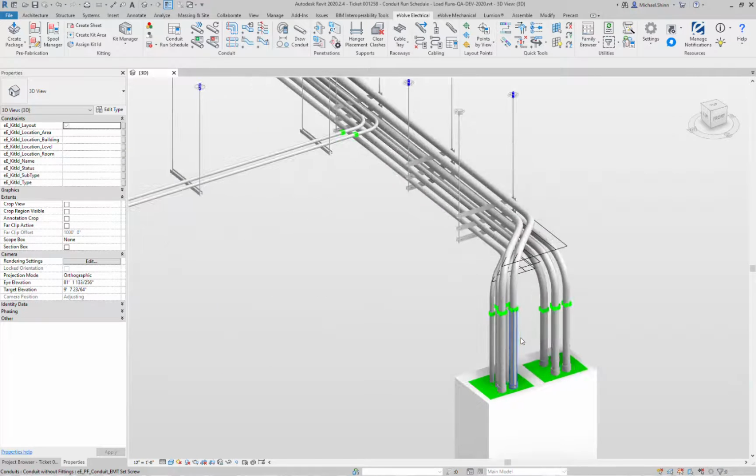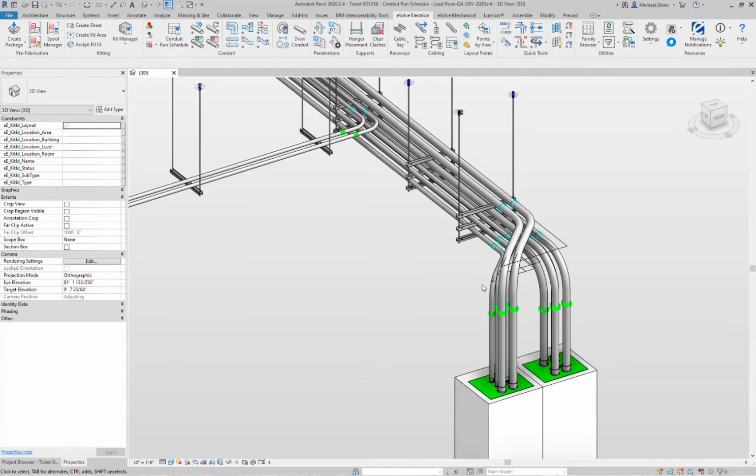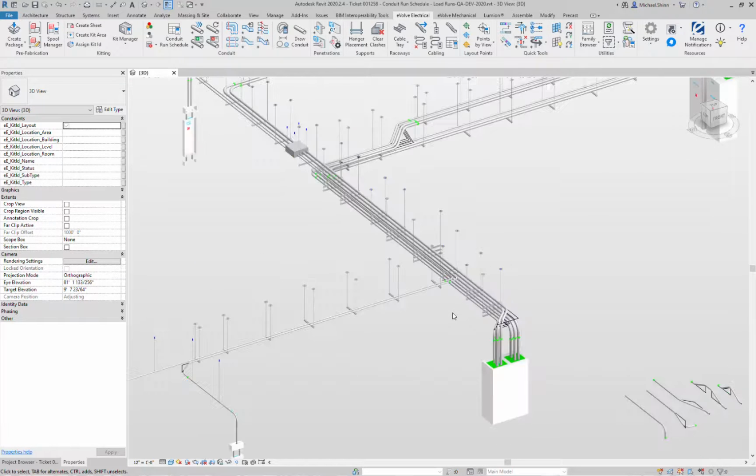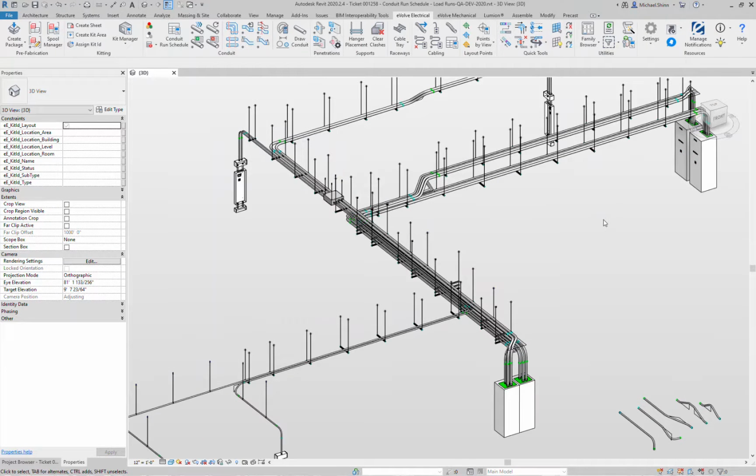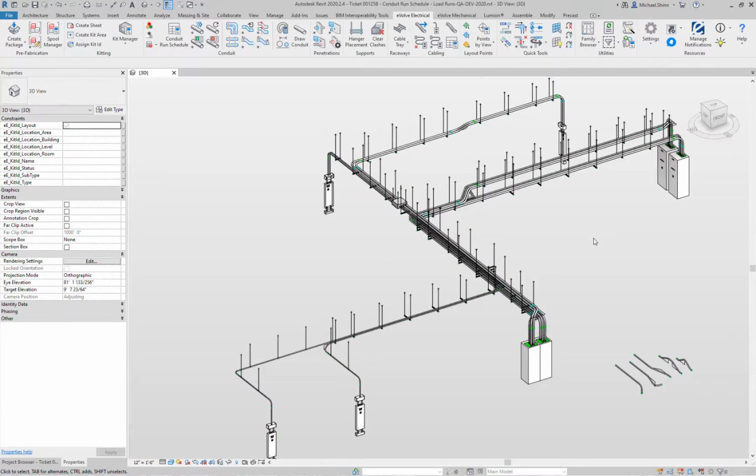In this case, you optimize your runs so that all of your bends and couplings are nicely aligned. This is the same method and procedure that takes place particularly on the piping and duct trades. They'll draw in all their models, and then they'll go back and optimize their runs for true prefab. So let's go ahead and do this process here.